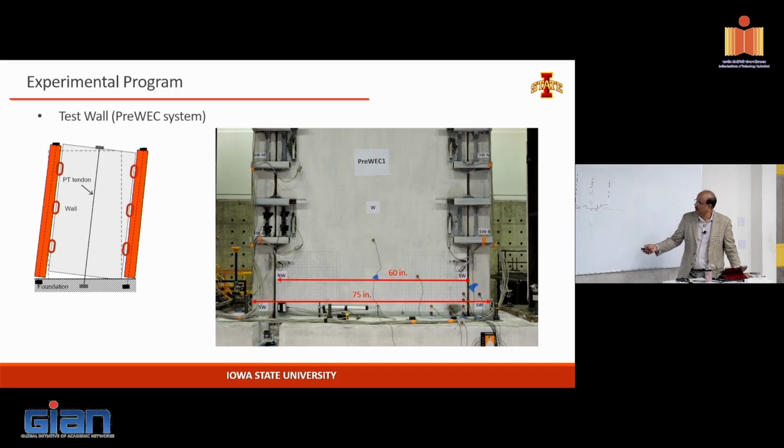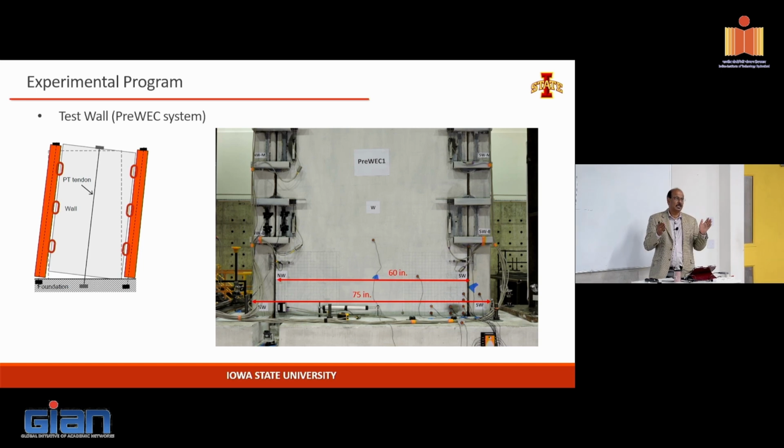That cuts down the wall, you could say drops it by 15 inches, so 7 centimeters or whatnot. That reduces the moment, the lever arm, so that will reduce your moment resistance, but you get additional moment coming in because of the forces generated along the connectors. So that's how we provide the resistance. The out-to-out dimension in both cases was the same.